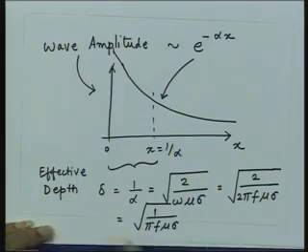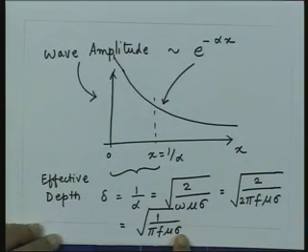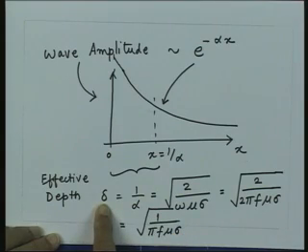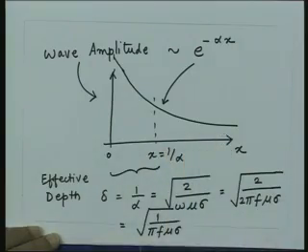Not only that, when the conductivity is infinite, that means if I take the ideal conductor, in that case this depth will be 0, that means the wave will not penetrate the medium at all. So, if you take an ideal conducting medium, there is no penetration of electromagnetic energy in the ideal conductor. Similarly, if I go to arbitrarily high frequencies, the depth of penetration becomes extremely small.